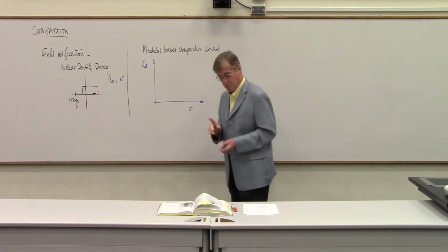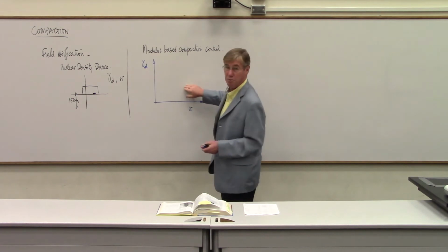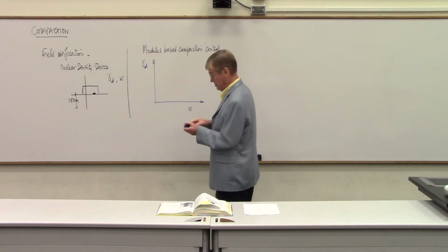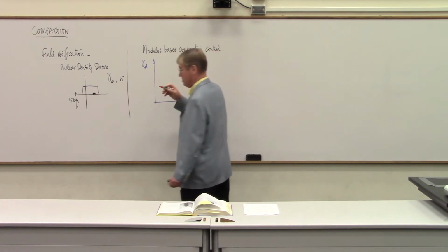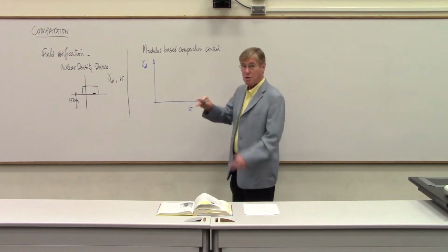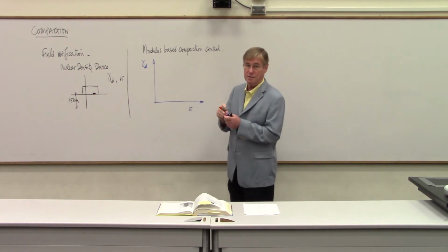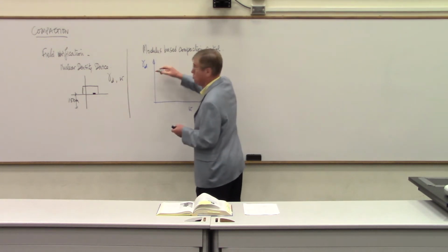One thing I wanted to point out when I drew that bell-shaped curve, you remember the bell-shaped curve that is obtained from the Proctor test. That bell-shaped curve has this pronounced shape because we don't plot gamma D from 0 to 20, let's say. We zoom in and we plot it from 18 to 21, let's say.